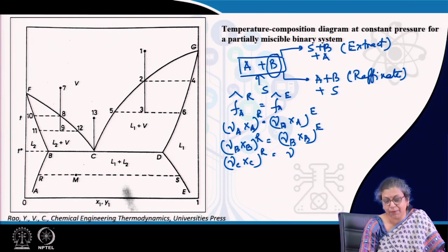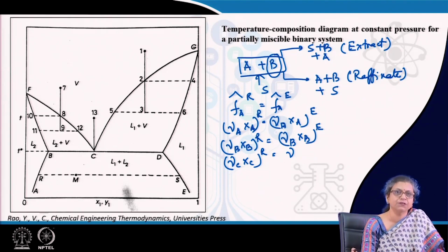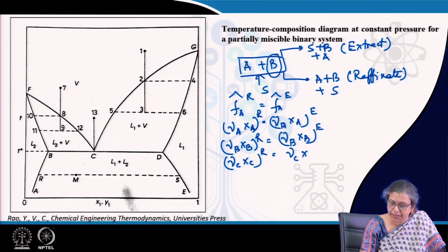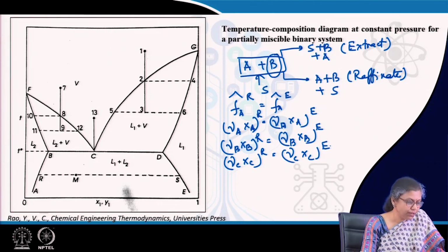So, therefore, gammas are extremely important in this case. The process of finding gammas is the same, but in most cases we have to include the gammas in the phase equilibrium equations written for liquid extraction cases.